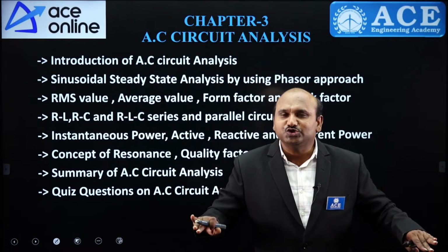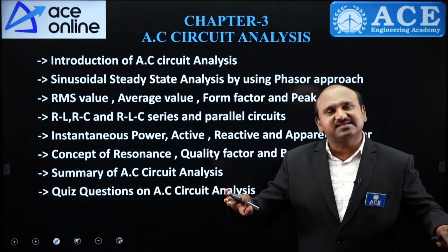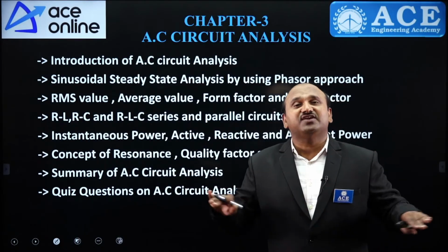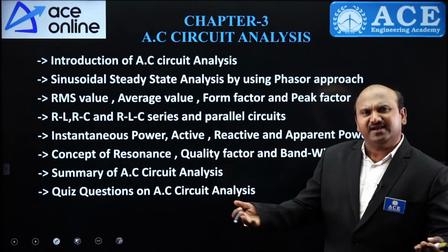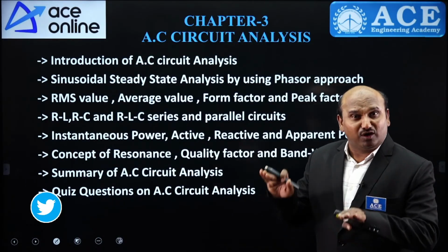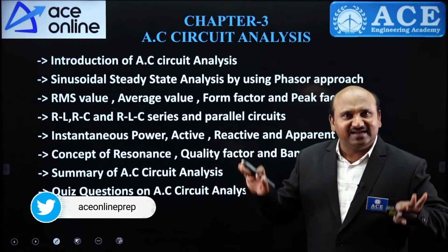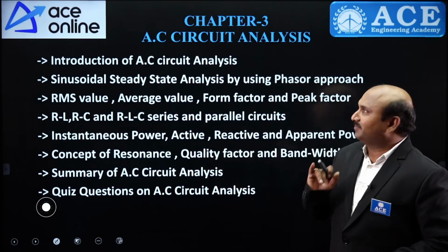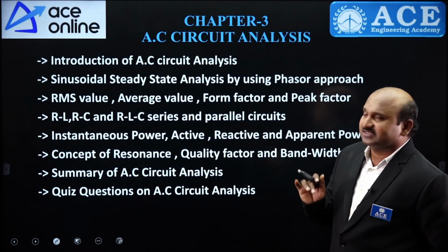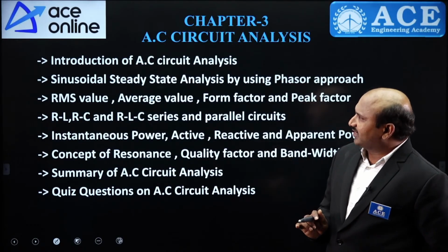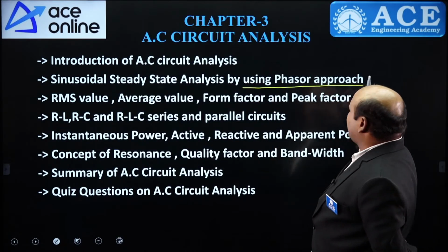Because under transients, the response is varying with respect to time. But in AC analysis, it is operating with a constant frequency. Usually, in our country, we operate at 50 Hz or a finite frequency, any frequency, which should be constant. The excitation's operating frequency should be constant. Then the network is under steady state. Remember that. And in the syllabus under AC circuit analysis, you need to concentrate on the introduction of AC circuit analysis, sinusoidal steady state analysis by using the phasor approach. This is very important here.